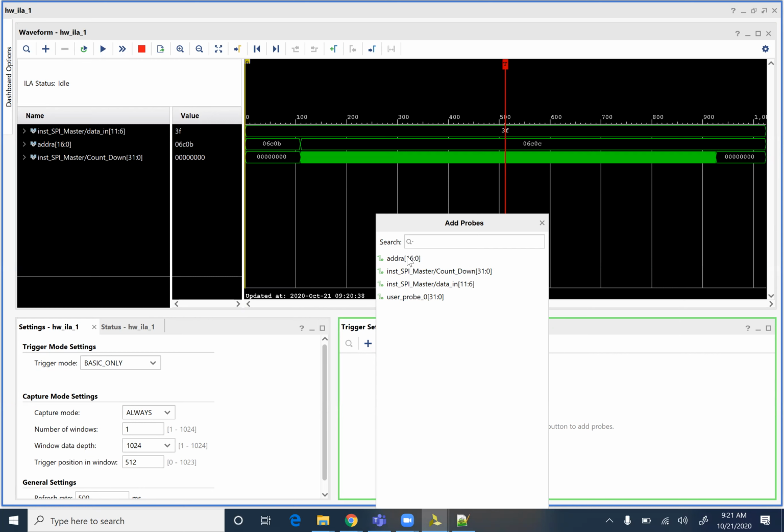A common bug that I've seen in the memory is that you've run through the sine wave and then it drops to 0 for some amount of time, and then the sine wave starts again instead of being a continuous sine wave. The reason this happens is usually that you're reading memory addresses that are out of bounds for what you've saved into it. So you saved 100,000 samples and you're trying to measure addresses from 100,000 to 131,000. That's going to give you bad outputs.